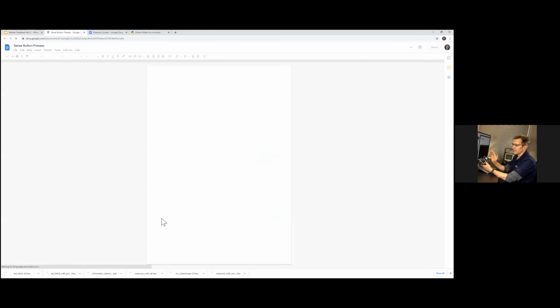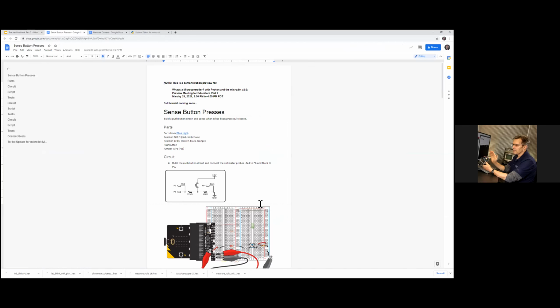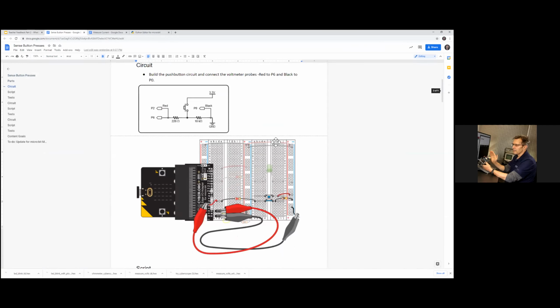Push buttons are something that unfortunately folks have learned to use basically just given a schematic and a wiring diagram, and they work okay in inventions, but there aren't many who are able to sit down and read the text and really get how and why a push button really works and why there has to be a resistor connected to it that's pulling it to ground.